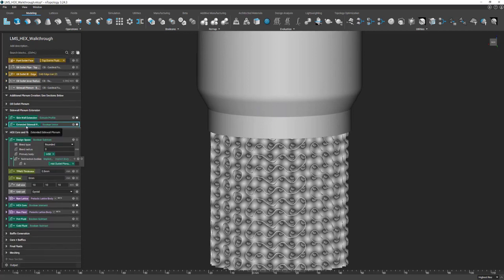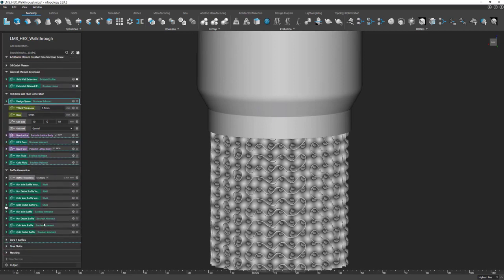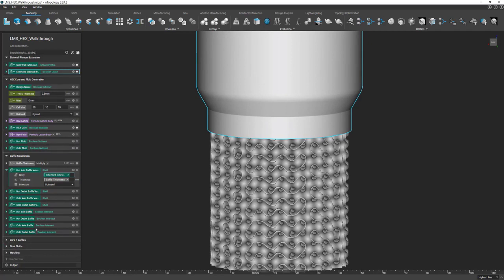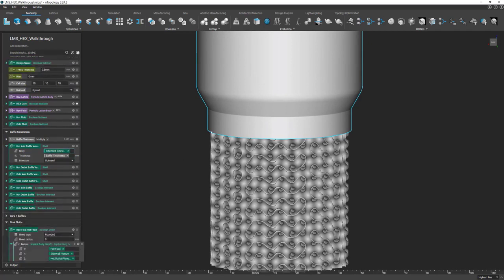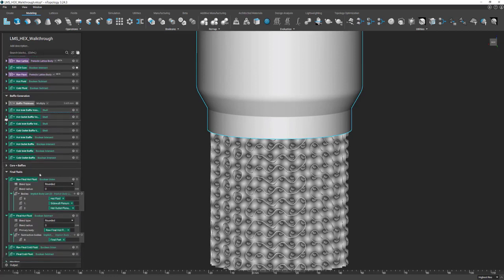Minimize these, and then we'll go through and do the same thing as we did previously, updating the various components. In this case, we don't need to remove from our design space, but we do need to update the baffling. So the sidewall is the inlet for the hot, so we'll come under the hot inlet baffle volume. We'll do our extended sidewall plenum in here. Our baffle is going to get automatically generated. The final fluid, we don't really need to update because there was just that small thin sliver there. And so all we really need to do in this case was update this baffle generation.